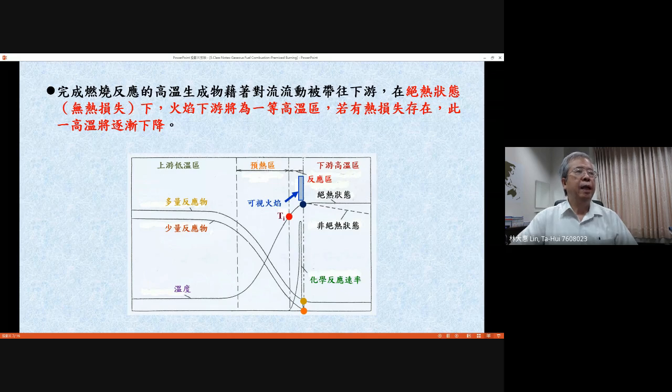Last time, I introduced the flow structures on a one-dimensional premixed flame, and we think about the structures like this. We have a premixed flame sitting at a certain position, and this stabilization at a certain position is caused by the supply of the premixture with a suitable feed-in rate. Actually, as I described earlier, why this premixed flame can sit here is because of the balance between the supply of premixture and also the consumption of the premixed flame.